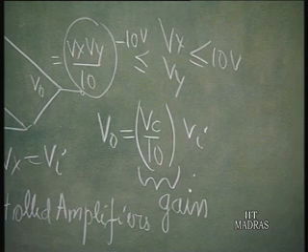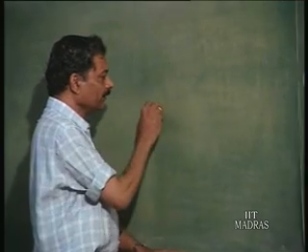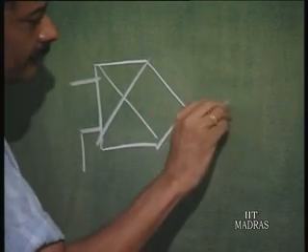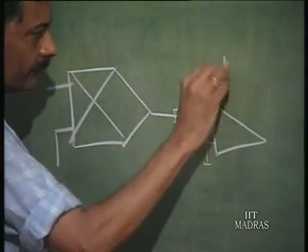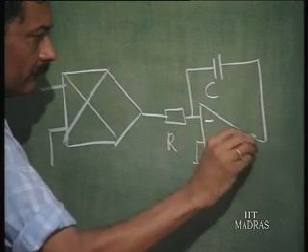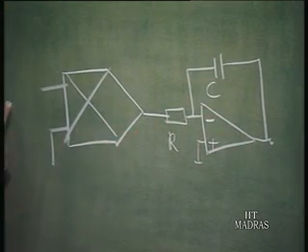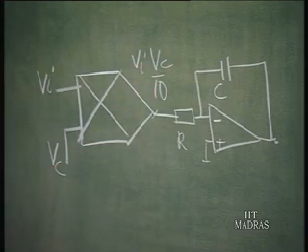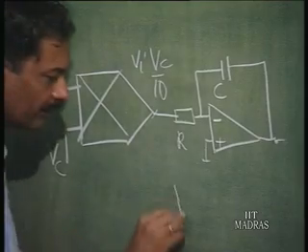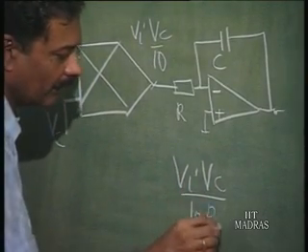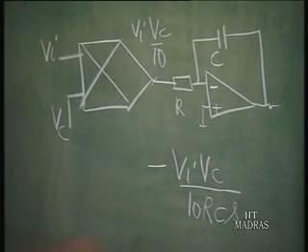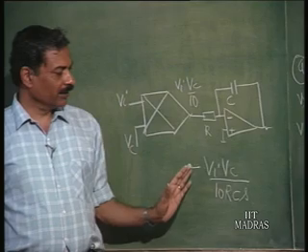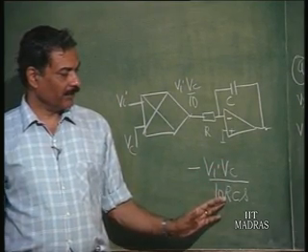Next, if such a voltage controlled amplifier is there and I use this in combination with, let us say, an integrator, let us see what happens. The normal integrator has the input here, but now I am feeding it the input through a multiplier. This is Vi and this is Vc. So, obviously, this becomes Vi Vc by 10. So, output now becomes integral, therefore, Vi Vc by 10 R C into S, okay, with a negative sign. Normal integrator output is minus Vi by SCR. Okay. So, now it becomes minus Vi by 10 into Vc, okay, by RCS.